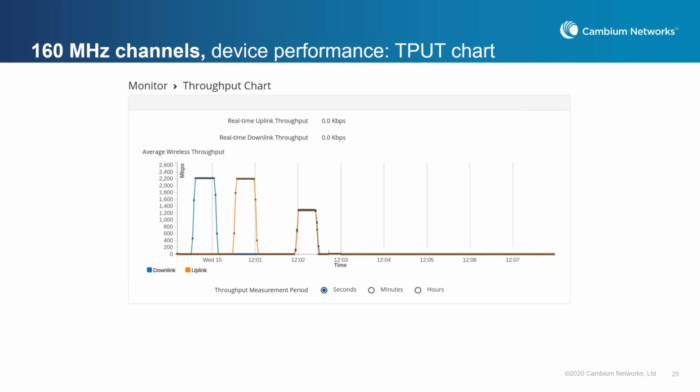So yeah, I guess the short answer is that because it hasn't been officially sanctioned and there are no products, the FCC has not certified not only the rules for 6 gigahertz, they certainly haven't certified any products in 6 gigahertz. For the outdoor, absolutely. I'm talking about fixed wireless for the outdoor for sure. The expectation is standard power, 36 dBm is what we're going to aim for. Our products are designed to go there. It's just a matter of getting that finalized and final guidance from the authorities.